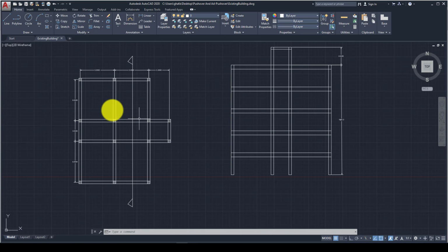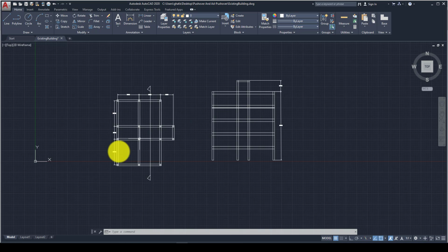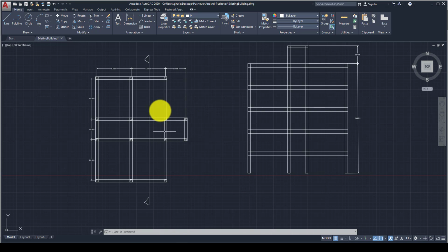This is an existing reinforced concrete structure with this typical plan, and these are the total stories: 1 story, 2, 3, 4, 5, and the core area is 6 stories in total. We will first evaluate this one, and then we want to retrofit using a bracing system. We're adding some extra braces in the perimeter. Then we will evaluate the response of the straining of the structure.